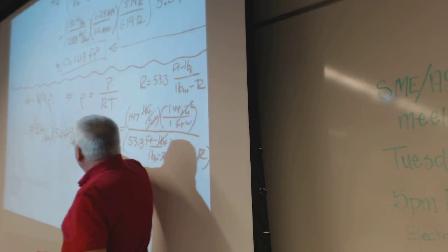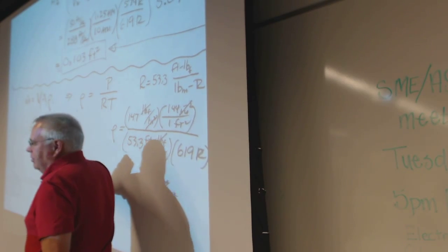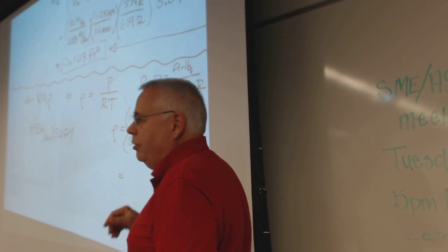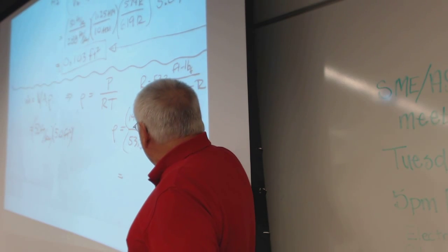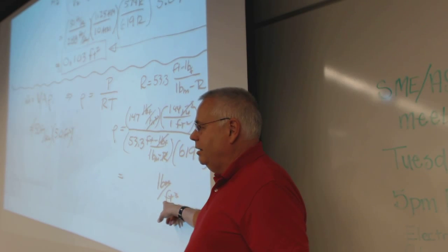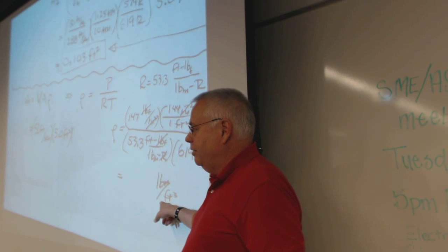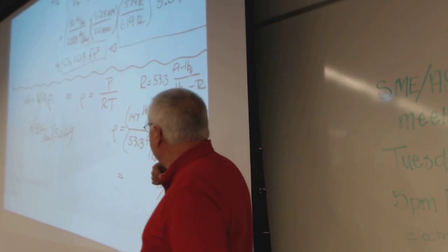I'm looking for the density to put in here. What we're taking to see just exactly what is the mass flow rate for that problem. And we're doing it from the inlet, because the outlet's the same as the inlet. So when we crank through the numbers, we're going to get the density of air at 10 atmospheres at whatever temperature is involved, this temperature.